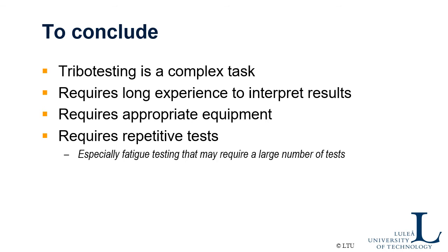But of course, you don't need to have $100 million machines available. You can still have a pin on disc equipment and measure the friction over time, and just study the surfaces in a microscope. Then you can learn something from that too. So there is of course a scale from relatively cheap to very, very expensive.